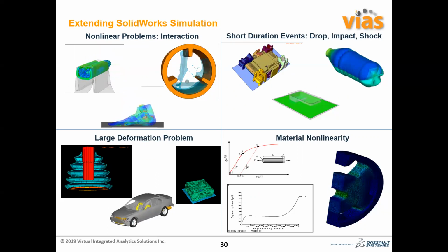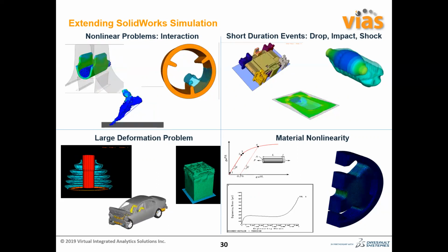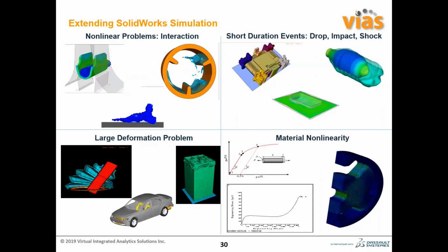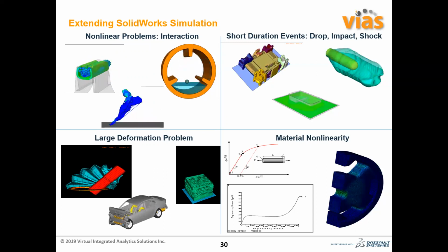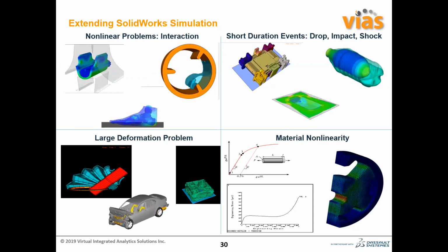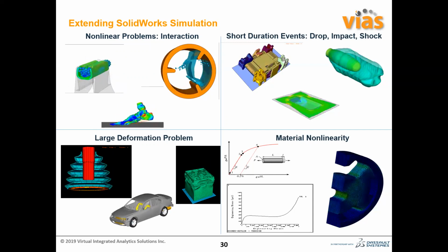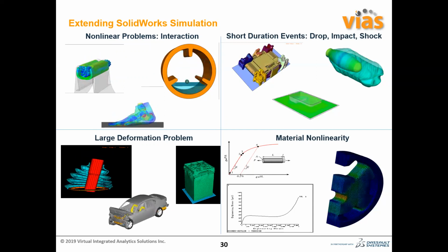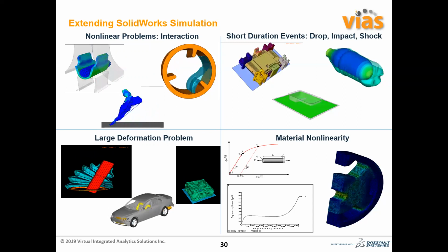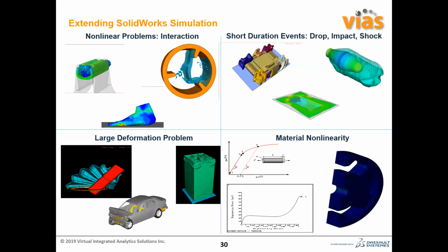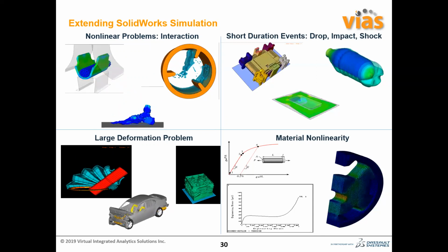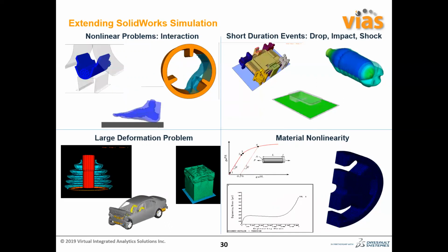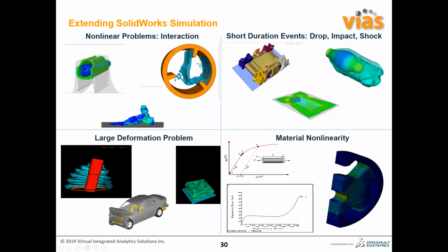We recently completed an analysis project that featured contact interaction between a scan model of a portion of the human body and a therapeutic device, and in all there were about 50,000 different unique faces interacting with each other. The contact capability of Simulia Abaqus was a huge asset in resolving a very accurate solution to the problem, but identifying the contact feature for each of those faces would not have been logistically feasible in SOLIDWORKS, because we would have needed to define all these contacting surfaces manually.